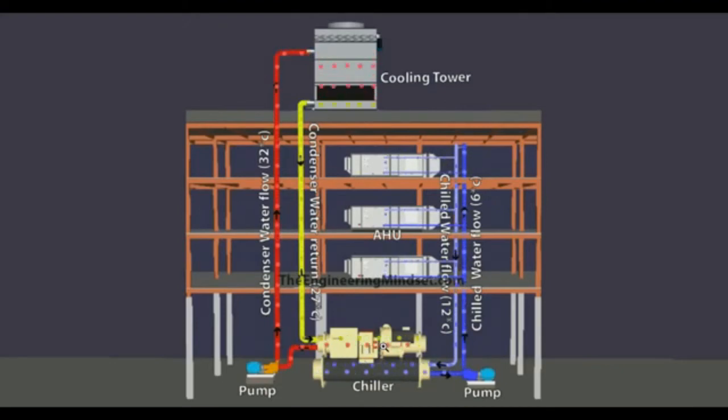And the chilled water system in this example is a central system. It's got to a point where having small air conditioning units on each floor is not going to be sufficient to provide the cooling that you need. So it becomes economical to install this large central plant system to produce that chilled water. And you may have more than one chiller. You usually have n+1, so the amount of chillers you need plus one more. If you're in a critical environment, you may even have +2 or +3. It depends on what that building needs, but we won't go too much into the detail of that.